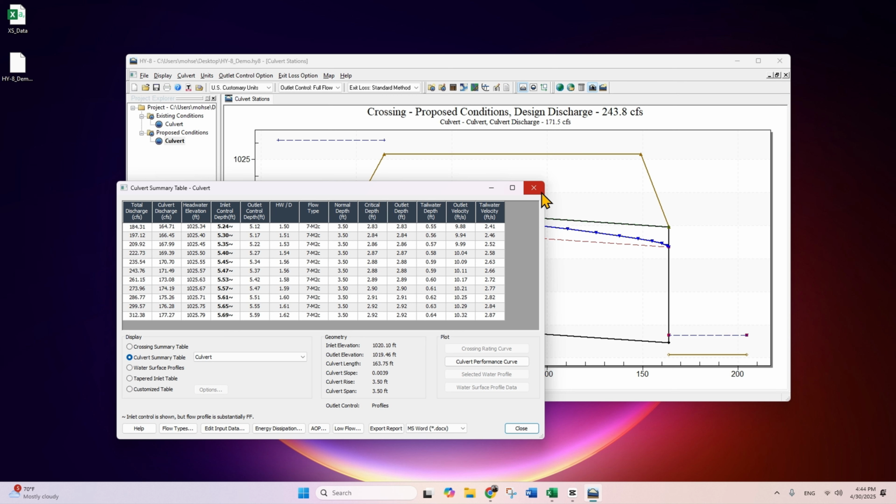Now, one of the things that I have explained in the GitHub page that I put in the description section is the concept of floodplain culverts. The floodplain culverts are usually smaller and they're placed a little bit higher, usually in the floodplain, to make sure that they capture the water that goes in the floodplain.